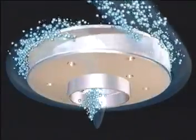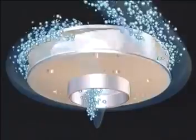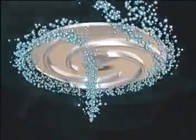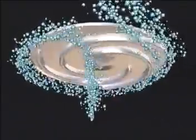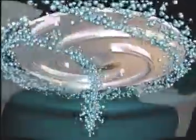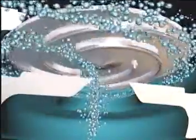Enclosed impeller designs incorporate a solid plate on both sides of the vanes. In the vortex impeller, vanes with shortened height are used so that the liquid and solids pass between the edges of the vanes and volute by whirlpool action.